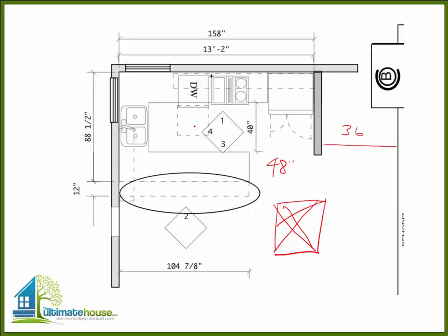In other words, you almost can't open this dishwasher and stand out of the way. So giving yourself a little extra room beyond the minimum requirements is oftentimes important, and it's important to know where to do those things. But as you design, take a little piece of paper on your plans that's a 4-foot by 4-foot shape and move it around and see where things get caught up.